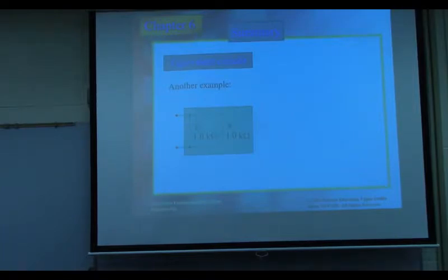Why is it half? 1 and 1 in parallel. How to calculate the parallel value? 1 times 1 divided by 1 plus 1, which equals half. So now you have a picture of this. That looks like this, 500 ohms, 0.5K. Again, there are no electrical measurements that can distinguish the 2 boxes. They are called what? Equivalent.